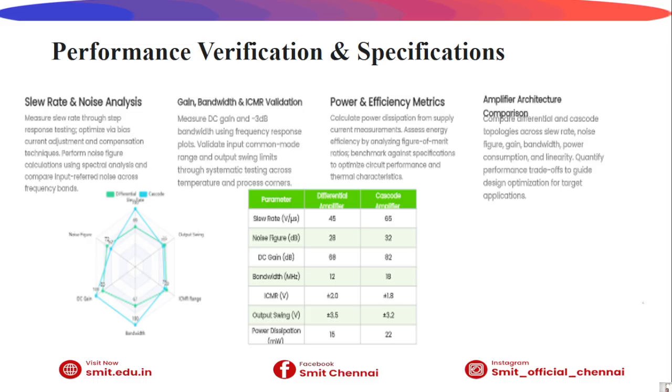We use specialized equipment like an oscilloscope, spectrum analyzer, and network analyzer to characterize the circuit. We verify its behavior under various operating conditions, different temperatures, supply voltages, and load conditions, to ensure robustness and reliability in the field. This step is where the rubber meets the road, confirming our design performs as intended.